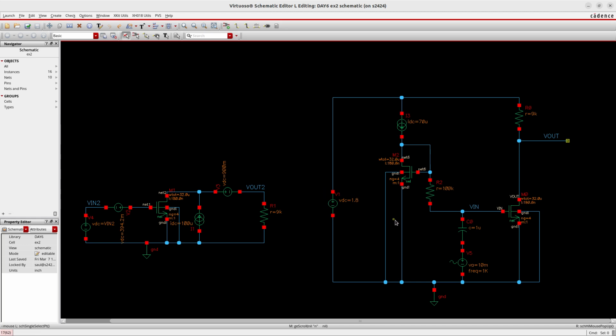We have the power supply, we have a current mirror, and then we have a transistor and the load connected to the power supply. We're going to discuss biasing techniques later during this course, so let's just assume that this is the way that we decided to bias this circuit. So I will show you the example with these two alternative circuits, because then you will appreciate how handy it is to be able to extract the static nonlinearity very early during the design.